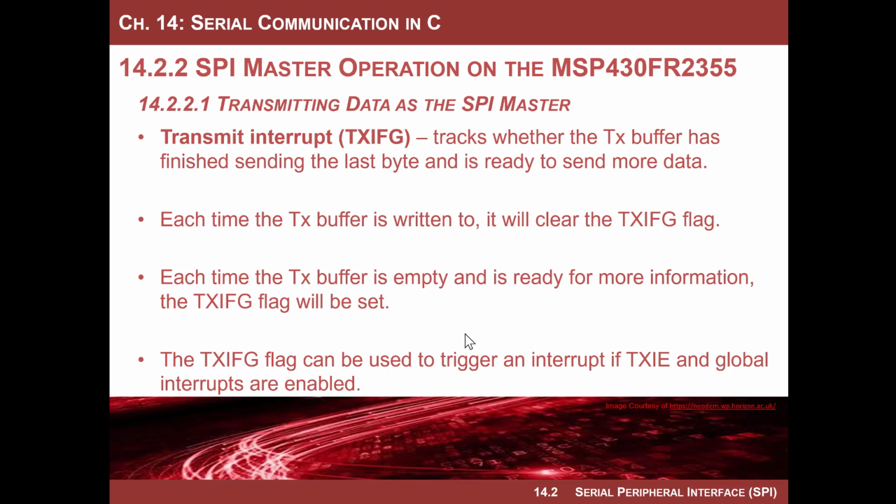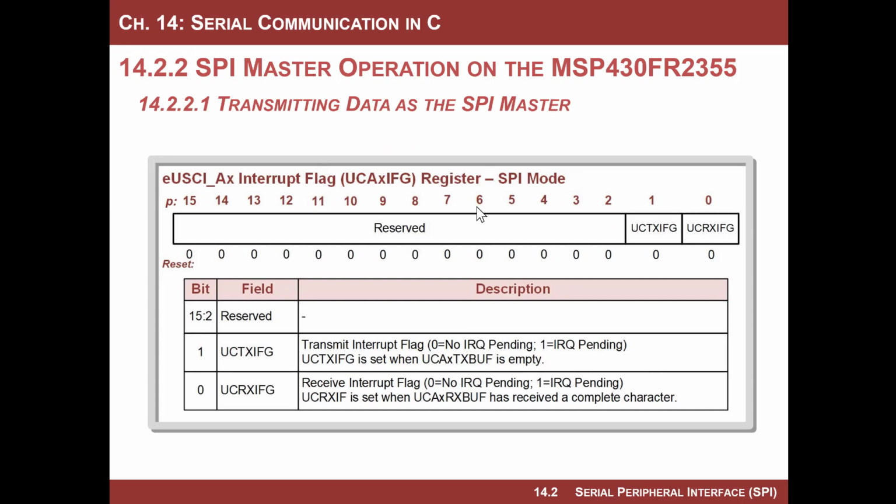Of course, if you can raise a flag, it can generate an interrupt. So you have an interrupt, which, since this is a peripheral, is maskable. The register is UCTXIFG, so that's the flag register. Keep in mind, this is the exact same spelling of the flag registers for the UART, except that when you are in SPI mode for a peripheral, they take on different values.